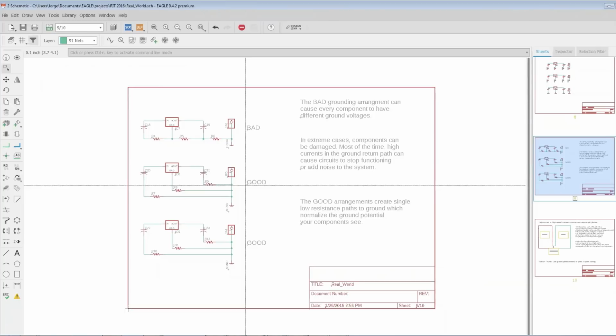Okay, we've enhanced our understanding of what ground is. Okay, most of the time you can think of it as an infinite sink, but that's not technically accurate. Okay, every signal has a return path. If you think in terms of signal path and return path, then things are going to be easier, because you're going to pay as much attention to the return path as you do to the signal path.